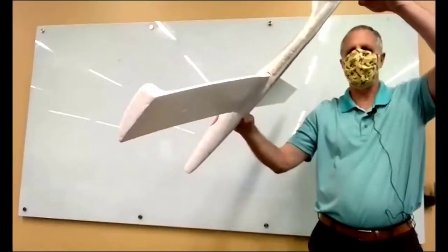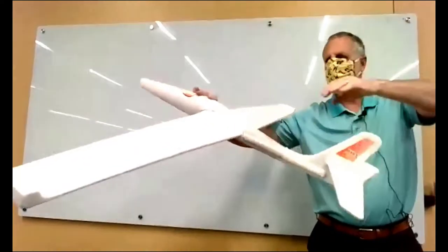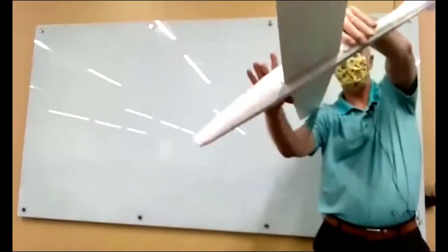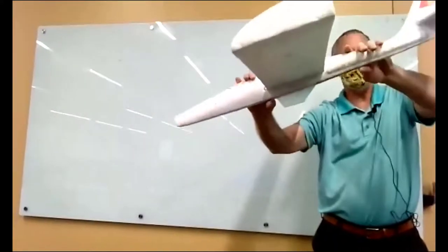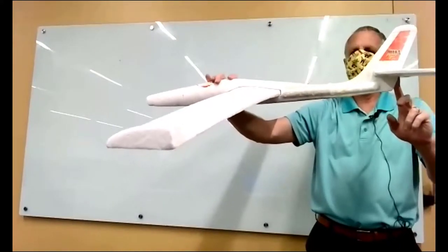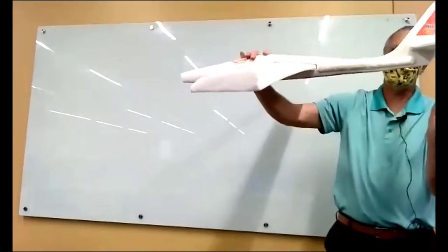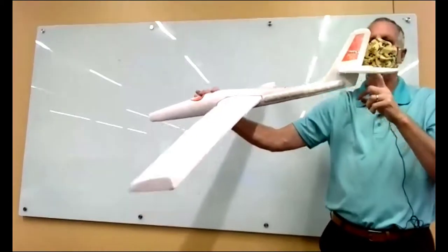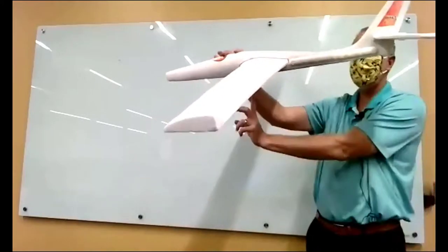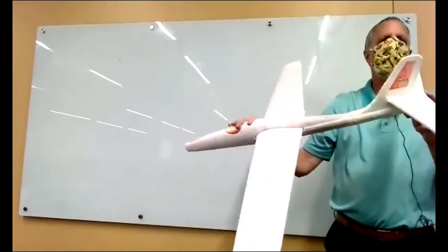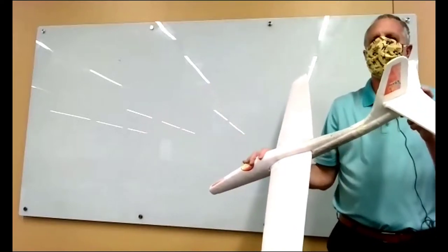This thing, right? See how it's sweeping down? There's air coming this way, right? So I'm exaggerating this. But as this sweeps down, it creates a relative wind from below in addition to the forward speed, and so it's increasing the angle of attack of the horizontal tail due to the pitch rate. It already has an angle of attack due to everything else. And so that's the added thing we need to add into the formula for the lift and the drag and the pitching moment.